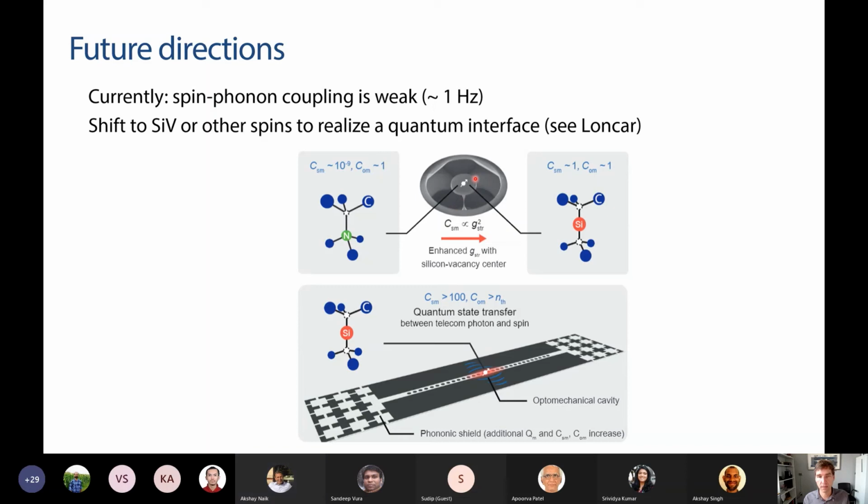I see. And said, well, let's try to make some microdisks first just to see what the limits of your fabrication are. Microdisks are very good for allowing you to quickly assess how good your etching is and what the limits for creating high optical Q cavities is. And then it turned out that their mechanical properties were also much better than we expected. So the mechanical quality factor is on the order of 10,000, which is a lot better than I've seen in previous microdisk structures.